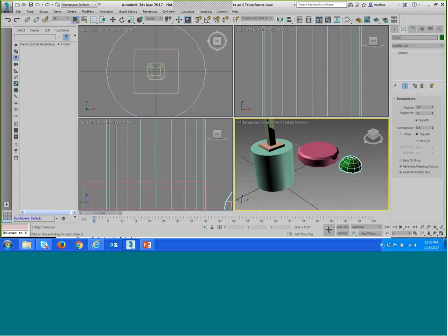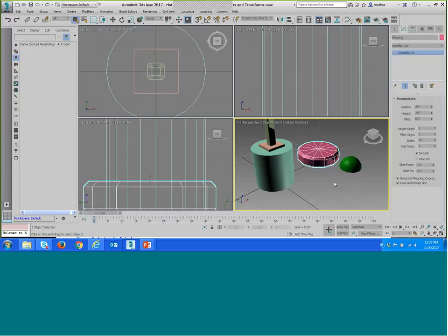So now go back, and now we'll move them into position using the actual transform tools. I selected the housing, and now you select and move right here, and you can see the gizmo is right here. This is the transform gizmo that I was talking about. And now you can use either highlight. When I move my cursor over one of the axes, it highlights it in yellow.